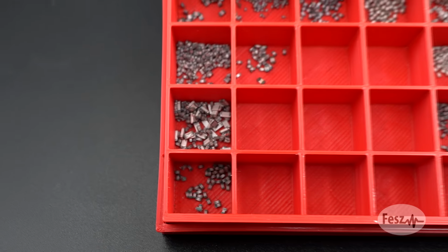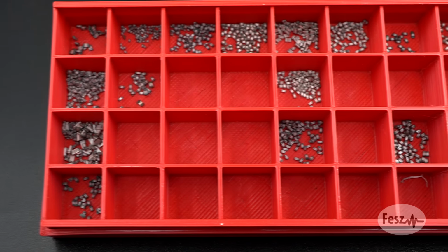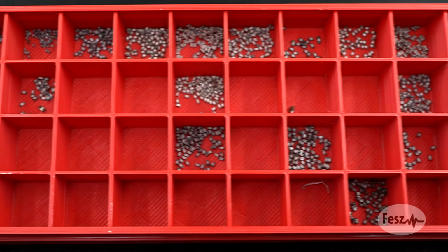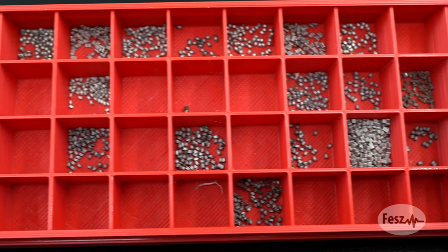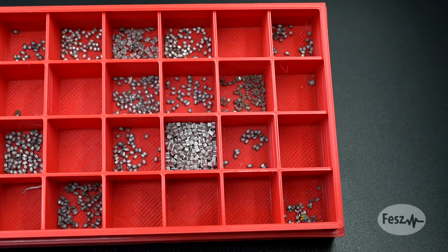Before building, it's important to consider that most RF filters for the HF band are made with the same types of components, capacitors and inductors. For the capacitor, it's usually simple. For small values, you just use ceramics, class 1 dielectric C0Gs. There are other better types of capacitors, of course, but these are the most common and the cheapest.